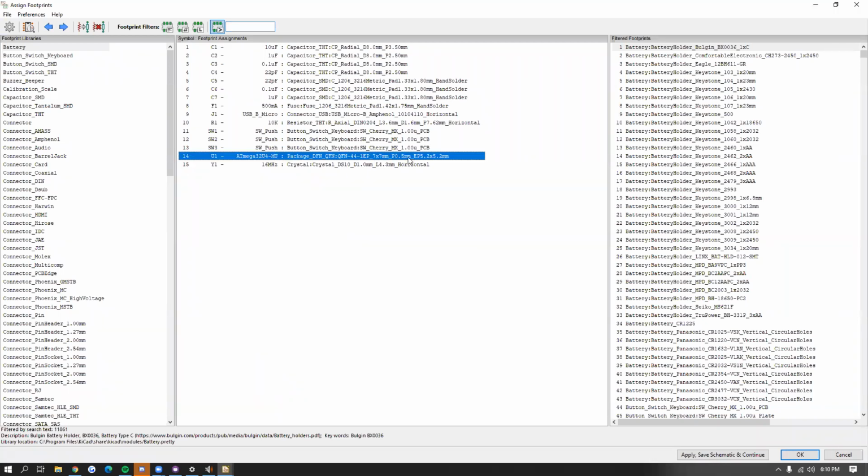And then it's this one right here, if you can find it, the one on my screen. QFN-44. Which one? There's a lot of. The one that says 1 EP 7x7 millimeters. P is the pitch, it's 0.5 millimeters. Oh, so QFN-44 1 EP 7x7 millimeters P0.5. There's no thermal vias, right? Yeah, no. Okay, I think I found it.